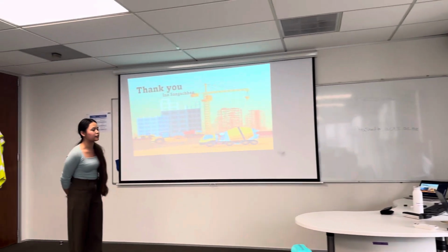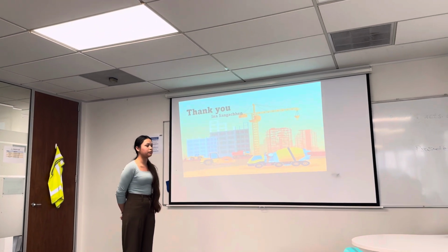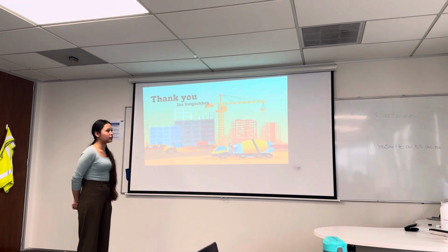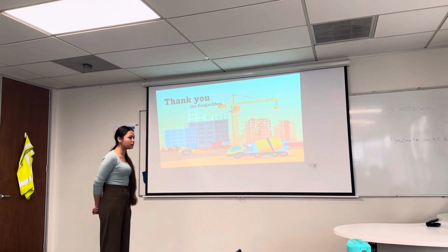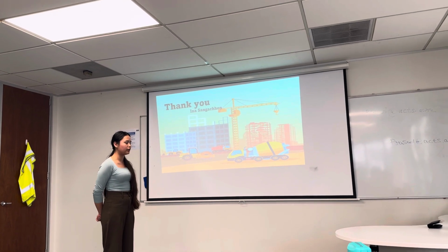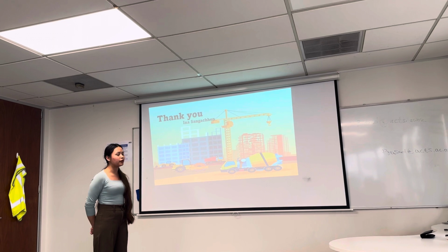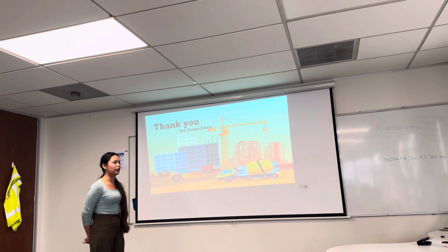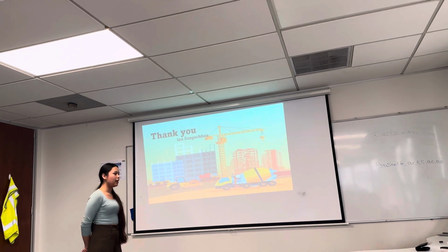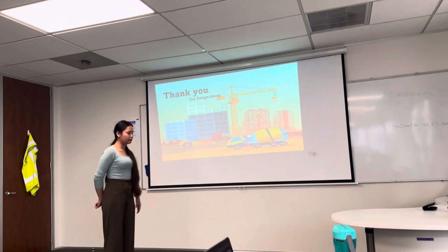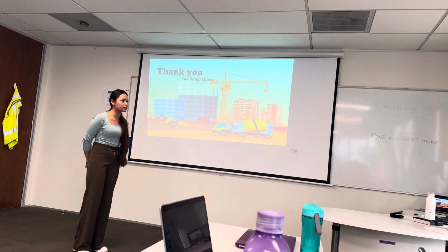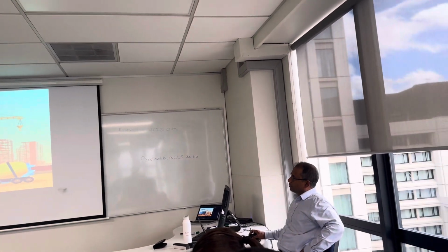What is the purpose of SOQ? The purpose of the schedule of quantities is that we mention the cost and the per hour rate of the labors, materials, and also we include the overhead charge for the company's profit margin. Also the indirect costs that come in the construction project, like rent and bills, those are included for that purpose.